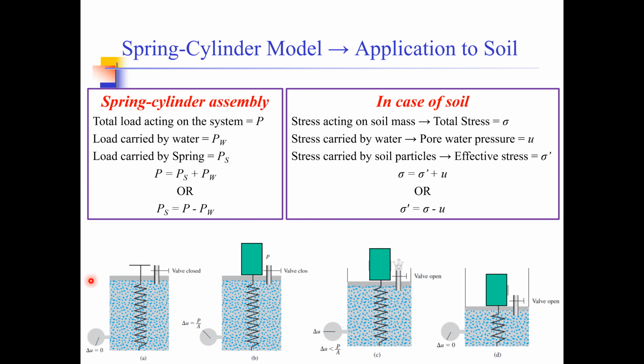We tried explaining how, when a load is applied on a saturated fine-grained soil, immediately upon the application of the load, the pore water cannot escape through the little voids that the fine-grained soils have. Because of this, the pore water pressure builds up within the soil.